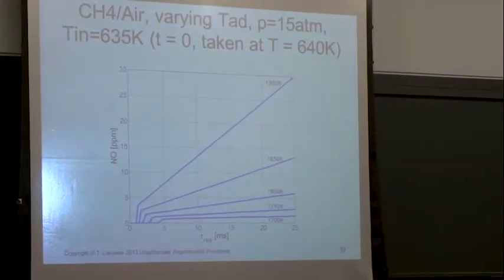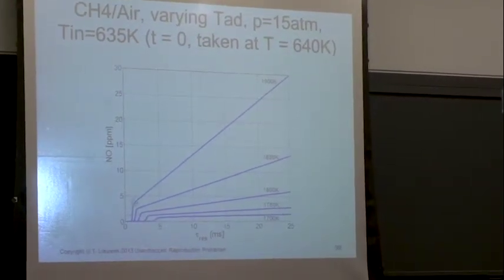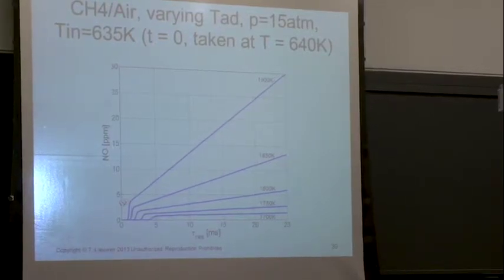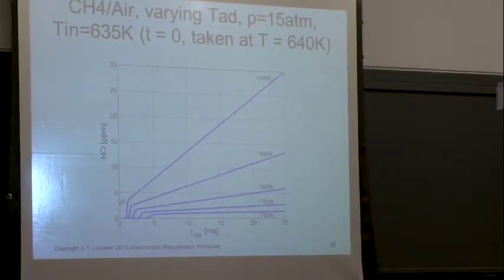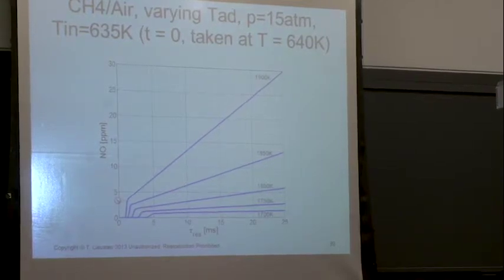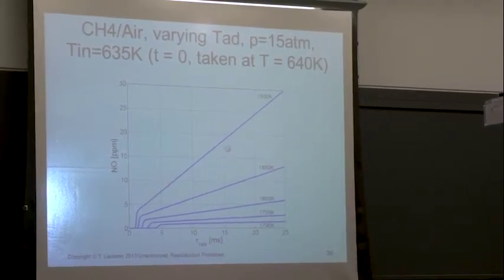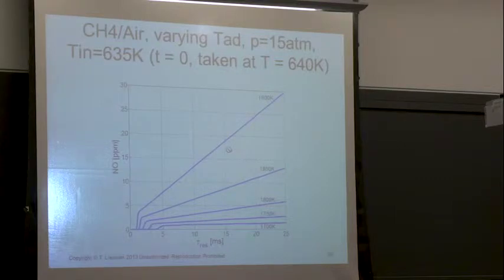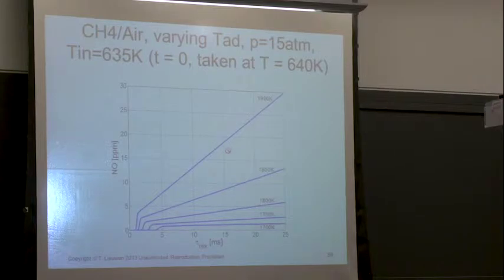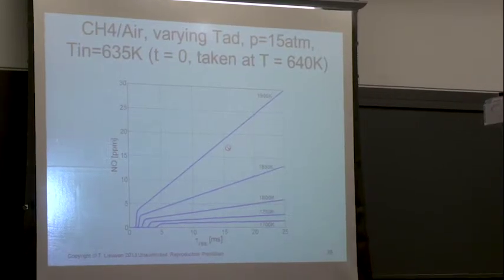So this is basically Zeldovich NOx or thermal NOx, and this is NNH, N2O, NO2, etc., those flame NOx mechanisms. In many cases, Zeldovich NOx is your dominant NOx producer. Also, for measuring NOx, in Europe you have EI NOx. What's the difference? Well, it's just for aircraft engines, you also use EI. I just chose to use ppm here, but you're right, it depends on where you are. So EI is generally grams of NOx, or kilograms of NOx, produced per kilogram of fuel consumed.